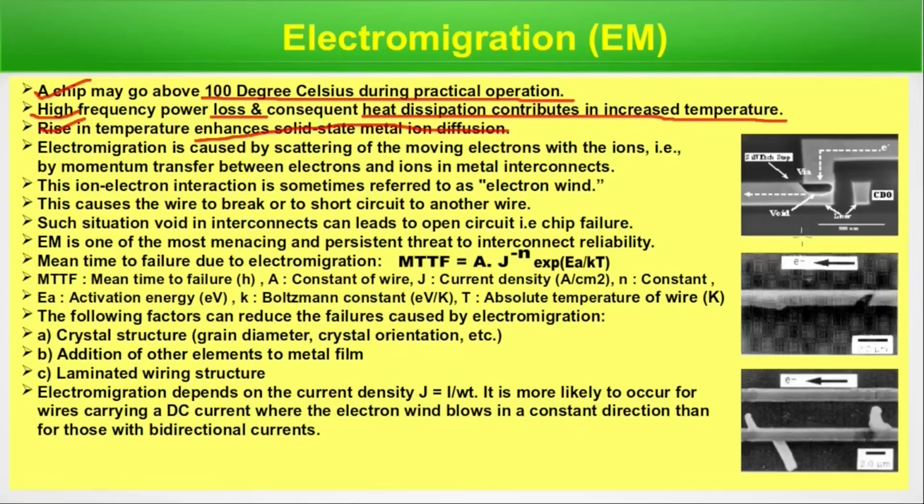If proper design considerations are not there, ions in interconnect can diffuse. Once they move from their position, that creates a void. That means disconnection or open circuit. If connectivity is not there between conductors, it's an open circuit. Either an open circuit void situation may happen, or, since it's at micro level and they're very close to another interconnect, it can move from its position and touch the other. If it touches another interconnect, then it creates a short circuit.